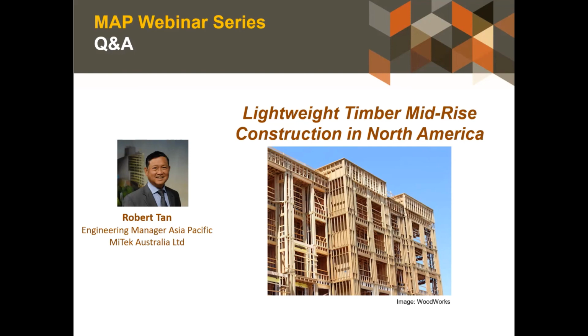They would be quite different. They would require some formwork, and they would require propping and other things like that for construction purposes. But the one that was done with the light topping is only very thin, not very thick at all, and they were just formed on the sides with the bottom plates, and they don't use propping on the underfloor for those loads.